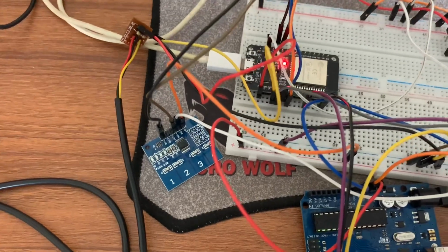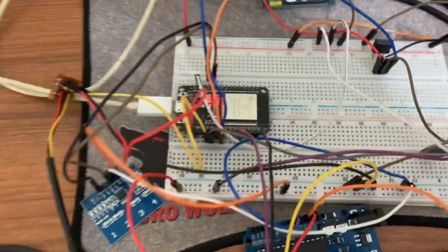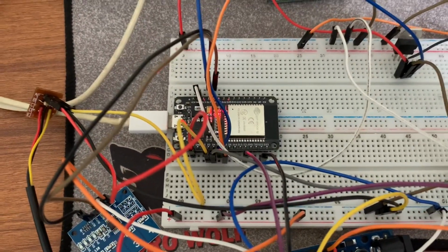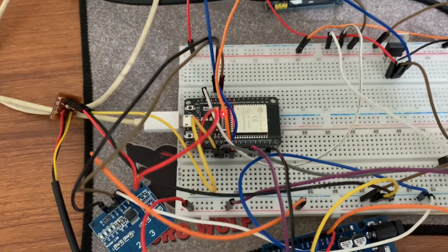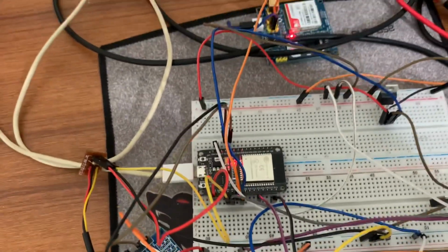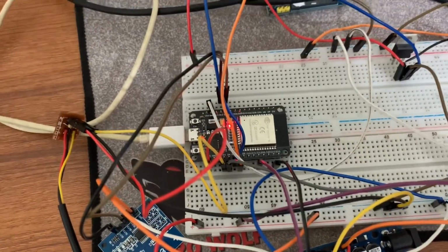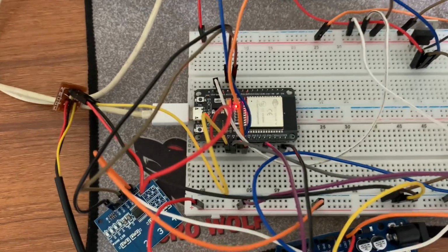Even if you are doing so, make sure that you are stepping down the data voltage. That's because the ESP32 board is not 5 volt tolerant. So if a sensor is generating a control signal of 5 volts, in case it's biased by 5 volts, make sure that you are stepping down the voltage with a voltage level shifter. You can use the DC to DC buck converter LM2596 in that case.